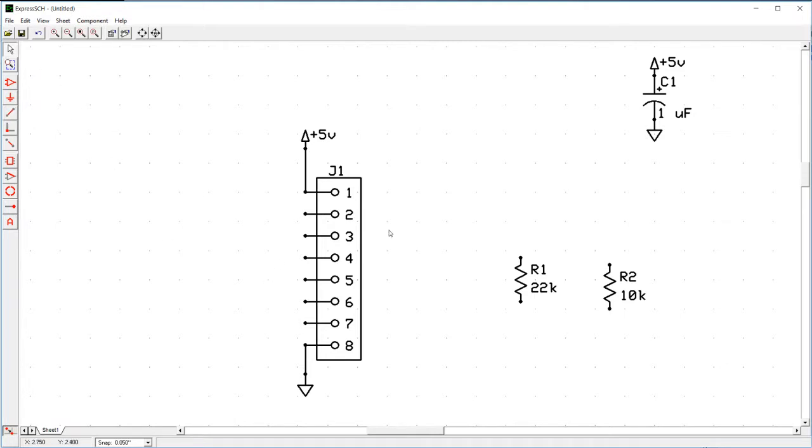So if I wanted to give my R1 a connection to, let's say, 5 volts, which is required, and then a wire to pin 7, I would place it, oops, escape key works in SolidWorks, it doesn't work here. I put in my nice right angles, connect it to 7, and then right-click to finish my line.